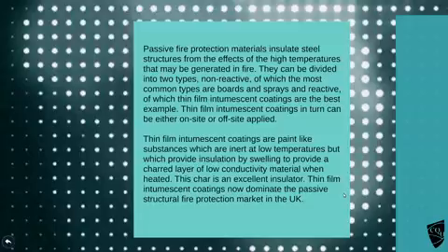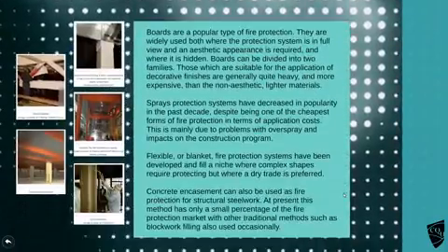Thin film, these coatings, they're quite inert, low temperature. They behave just like a paint, but they swell up into a charred layer. That's what I just said, isn't it? They're quite common in the UK and Europe, but I don't know if they're so common in Australia at the moment. And then you get things which are more likely to see, the more physical ones.